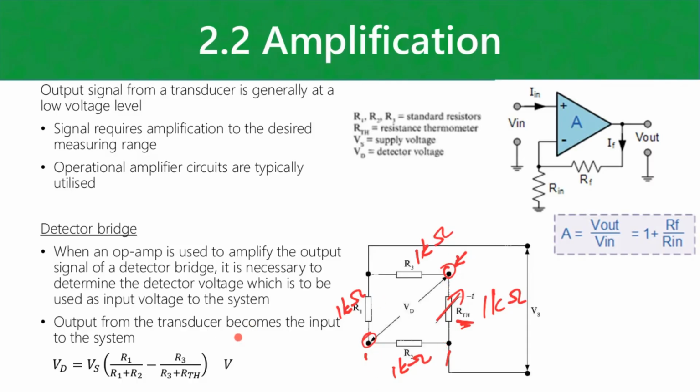You can see in the formula for the output voltage across the bridge that's essentially what you're going to have. You'll also notice that if all the resistors are the same size, the difference is going to equate to 0. So this portion and this portion are going to be the same, thus 0 difference in voltage.